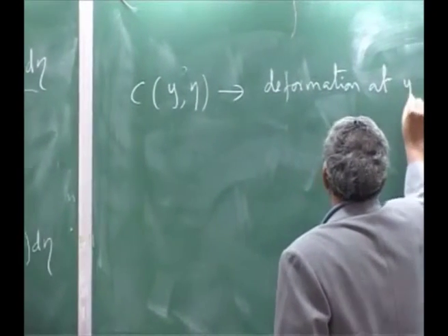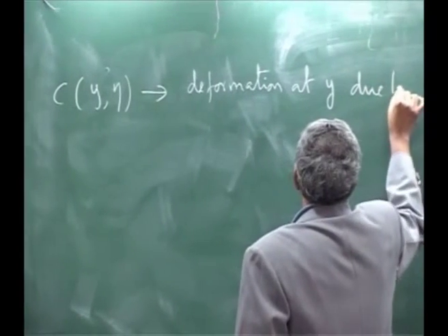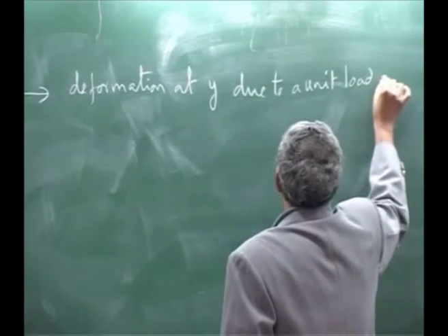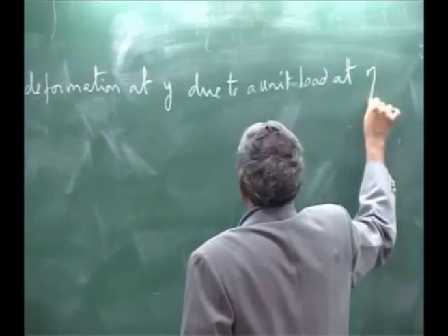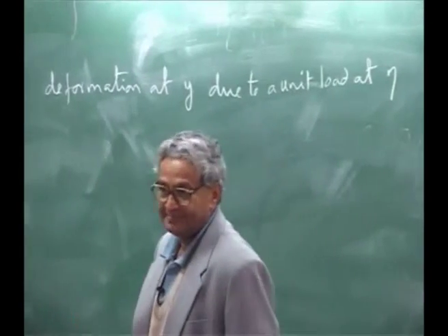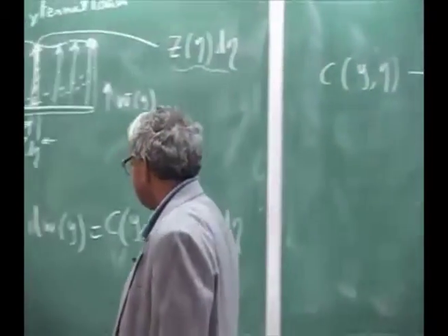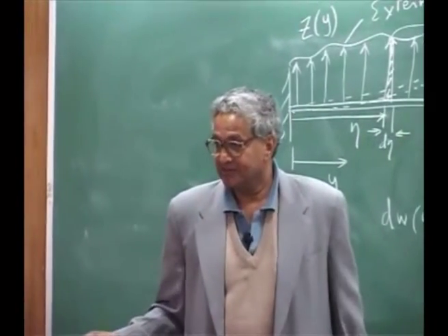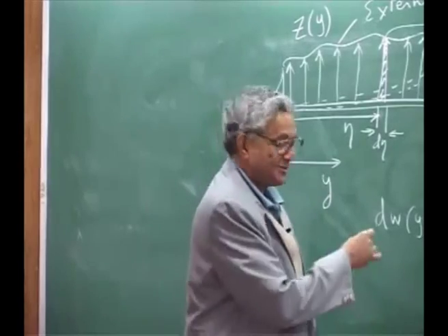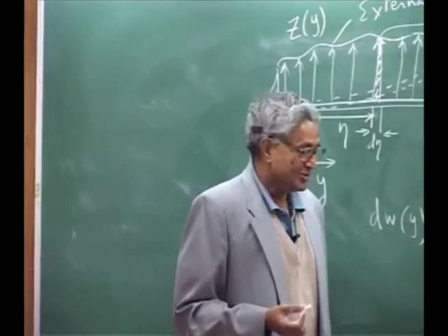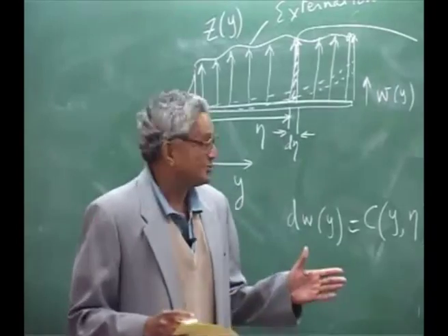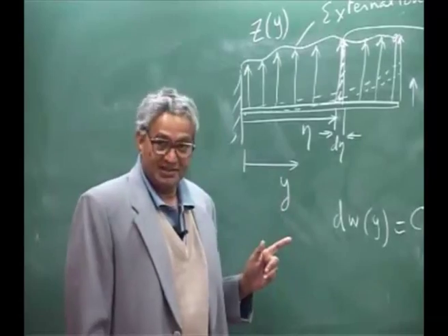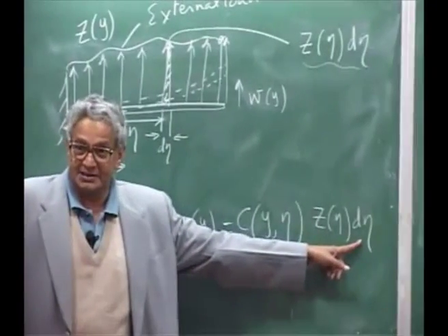the deformation at y due to a unit load at eta, okay. Now if you want total deflection, what you have to do is you have to integrate. So total deflection means deflection due to all the loads. Now that integration is over d eta.